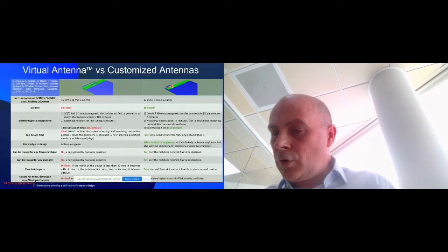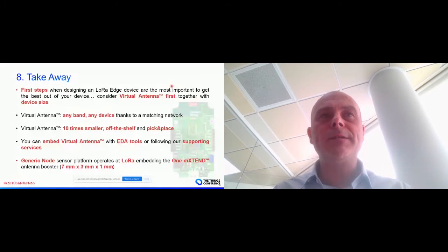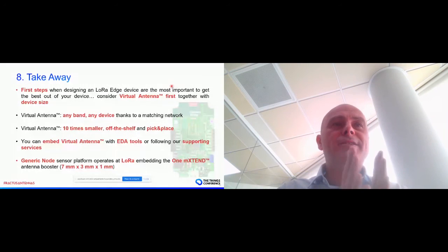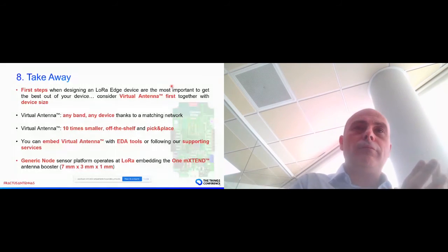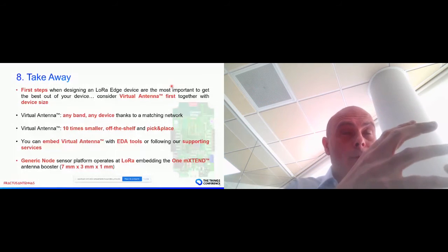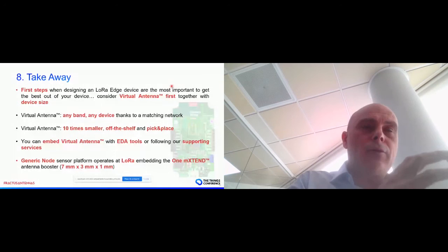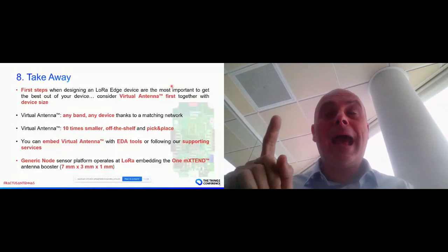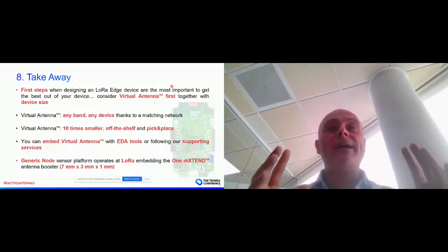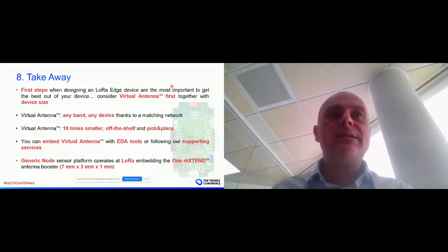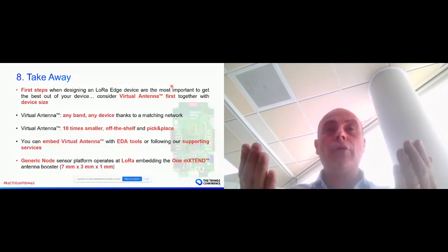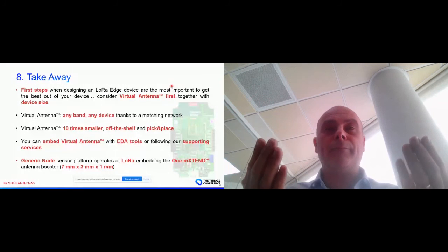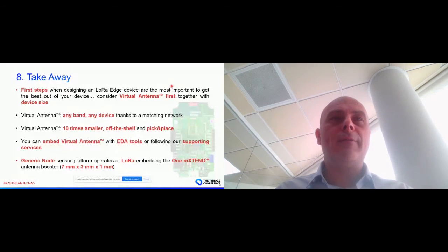So just to conclude, some takeaways, some tips. First step, as in a chess game, the first step matters a lot. So you should consider the virtual antenna not only as a component, but as a system. So decide which is the virtual antenna, the position of the booster on your PCB, and most important, also the device size. We should collaborate all together and have as a trade-off not only marketing decisions, but also performance in terms of radiofrequency performance. You should choose the device size.